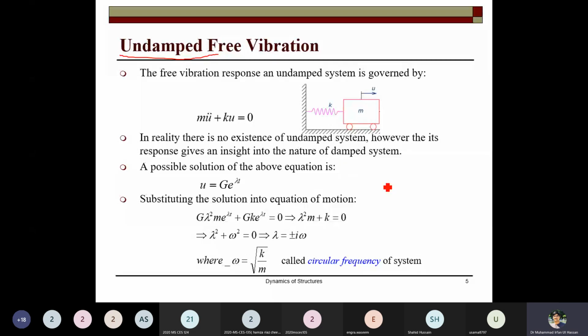Basically, we are studying the undamped system first so that we can exclude the effect of damping, and the same things will be discussed with the inclusion of c. So first you must prove the different relationships and see what happens when the system is in undamped free vibration, subjected to no force, but with some initial displacement or initial velocity given, and how the different graphs of displacement versus time are formed.